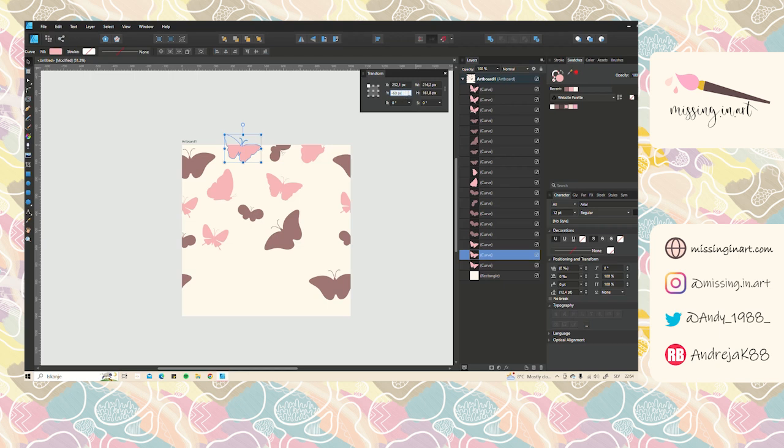So when we want to copy things from up downwards, we select the object, copy and paste, go to Y and press plus 1000, and there it is. Again with this one, copy, plus 1000, and this one, plus 1000.